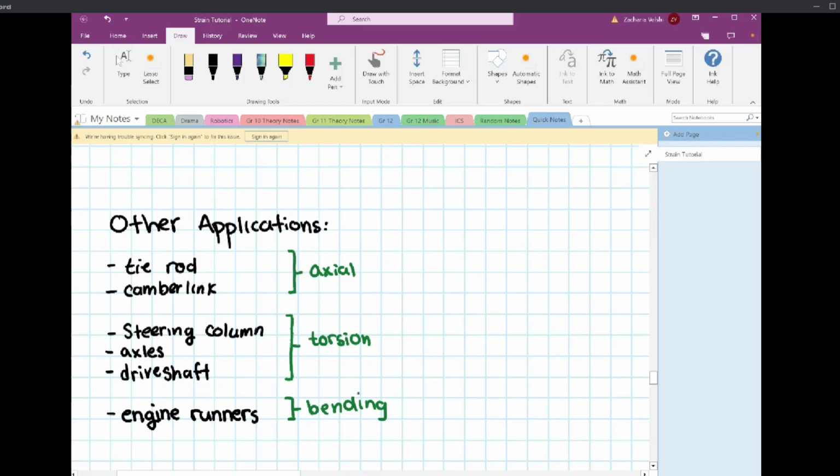And then engine runners, I was talking about it with Anshul and Brennan a little while ago. It's pretty cool to do engine runner strain gauges to actually see and validate, sort of complete that design cycle for the engine runners, to be able to design them to be as small as possible and still take all the vibrational load from the engine, and then see how we can minimize the material selection for that, because right now they're insanely overbuilt. That'd be pretty cool.